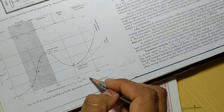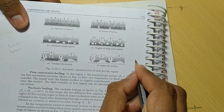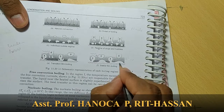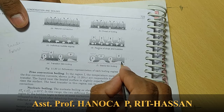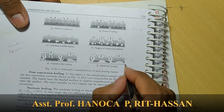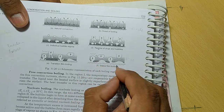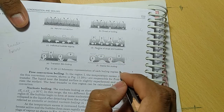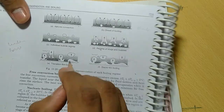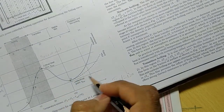After this point, as we further increase the excess temperature, the heat flux Q goes on increasing. See, the thermal conductivity of the liquid is high compared to the thermal conductivity of the gas, or of the empty space, because of the bubbles or a film. Here the thermal conductivity is less compared to the liquid, so the heat transfer automatically reduces. So the Q will reduce here.